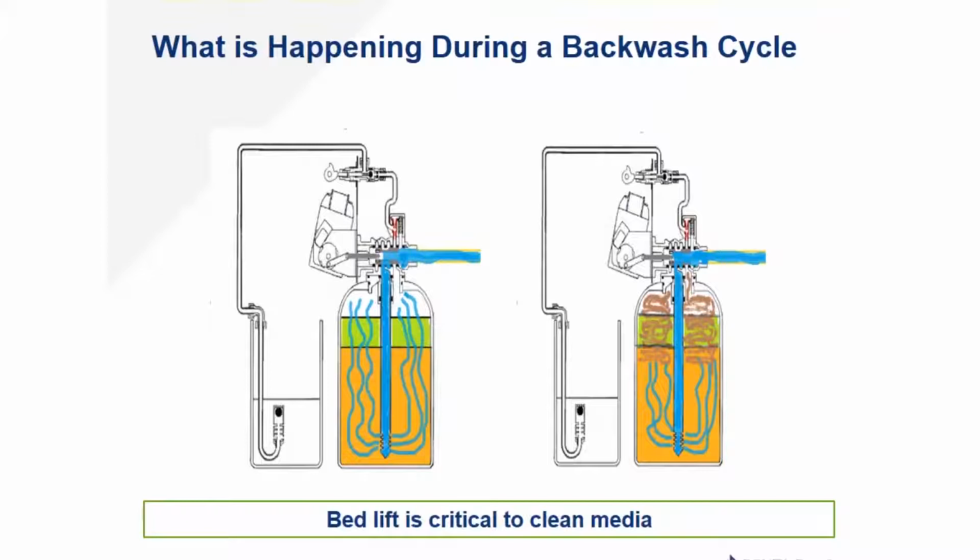But what we're really trying to do is lift this bed up to free up space to allow the dirt load to come up and off the resin or media and go out the waste line. And this is critical to understand because this dirt load coats the media. And if you don't have good contact with the water, the media really cannot react and interact with the water the way we want it to. So dirt load over time impacts capacity and the ability for the media to function.